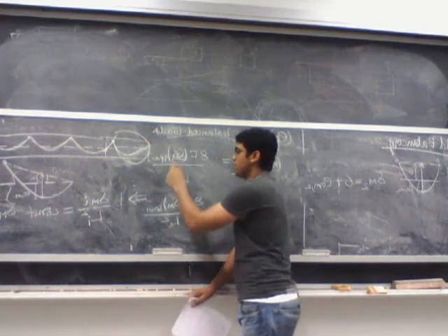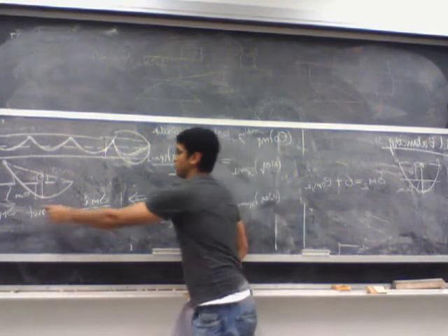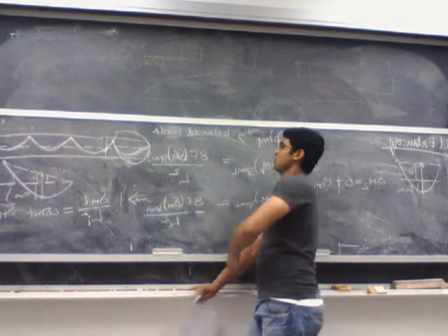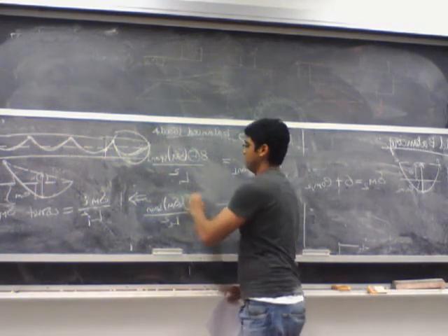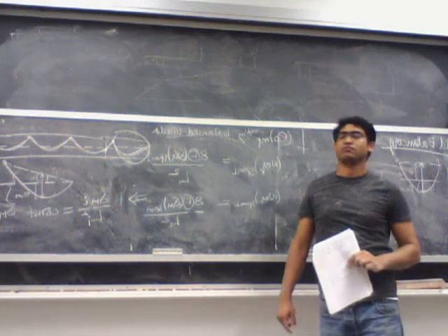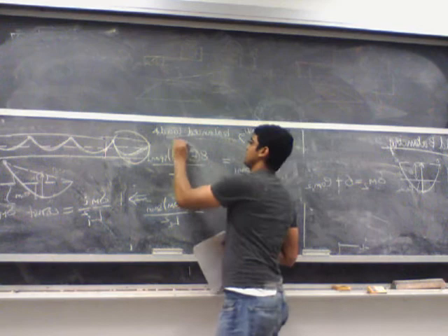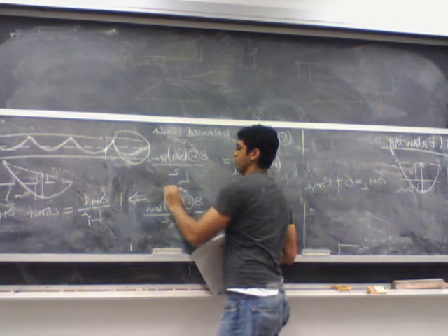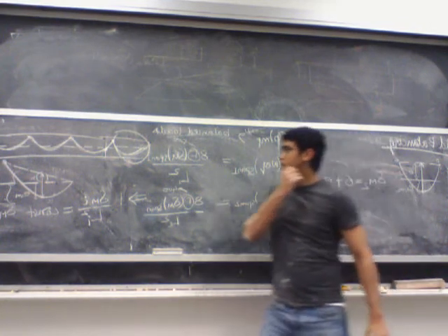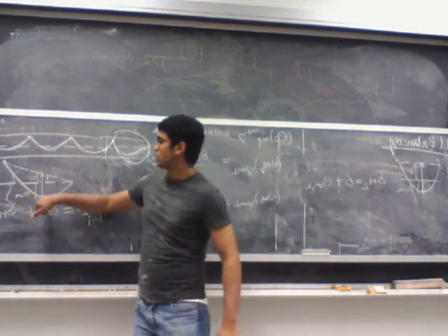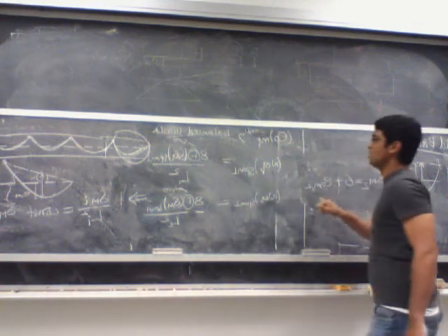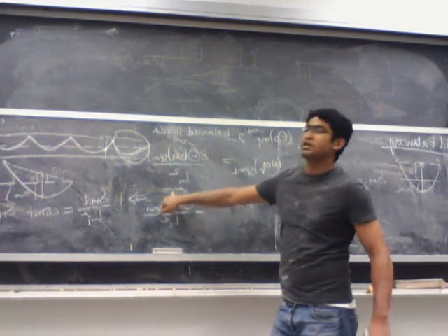So you'll plug in the value of delta m for two different spans. For the first one, you'll plug in 15 inches. For the second one, you plug in 18 inches here. You calculate the value of f. Most probably 99% of the time, you'll actually get two different values from both the spans. Let's say you get 500 kips from here, and you get 400 kips from this one. So in order to make E naught equal to the maximum possible, you need 500 kips. And on this span, in order to maximize this, you actually need only 400 kips.